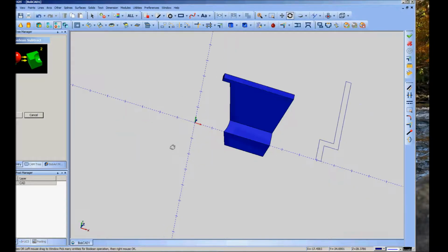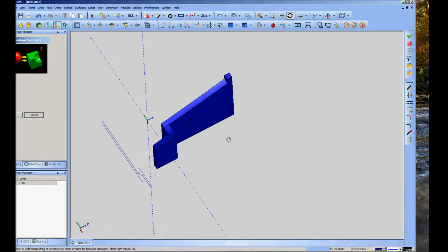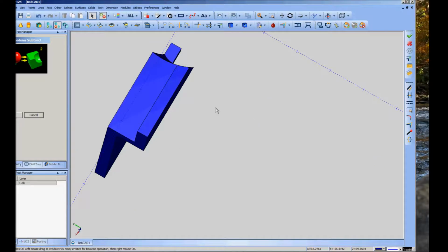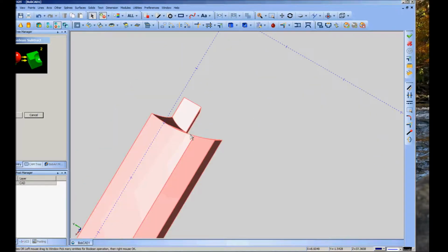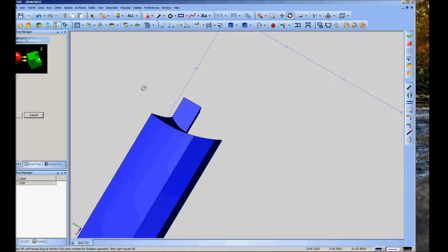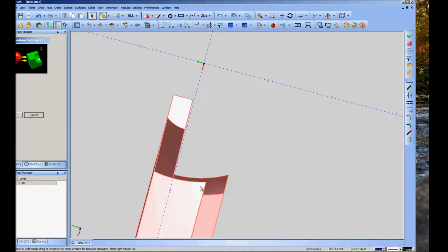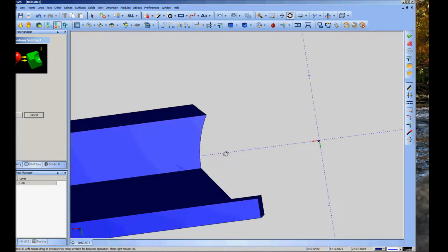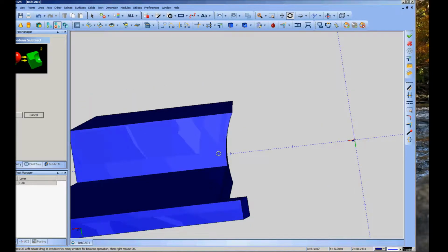Click OK. Now the thing I want you to notice here is that as I rotate this up, this solid that we constructed has now taken the outer curves of that cone. So it's got a broad curve at the base, it's got a much narrower curve up top. What that's going to allow you to do is cut for a set distance into your cone.